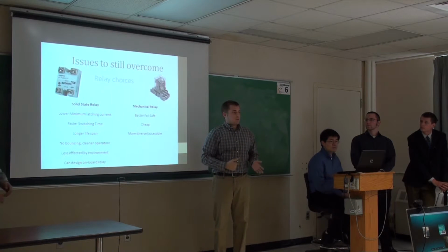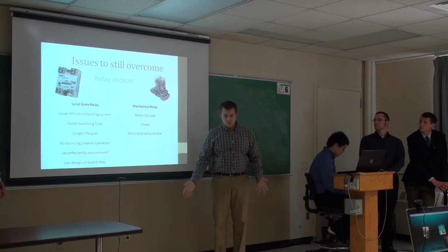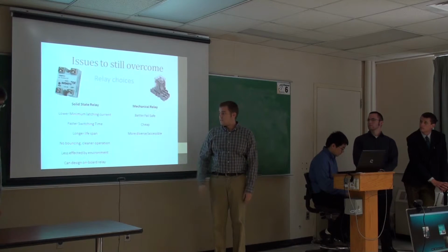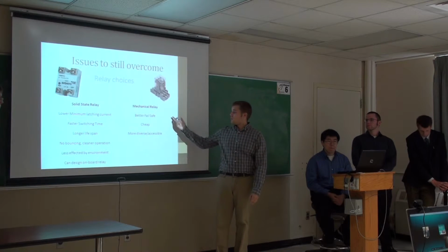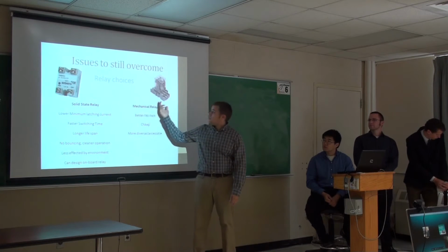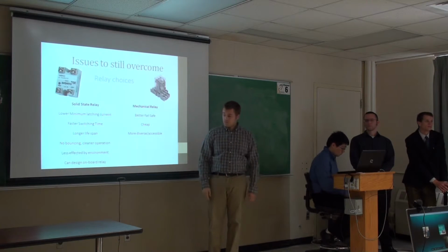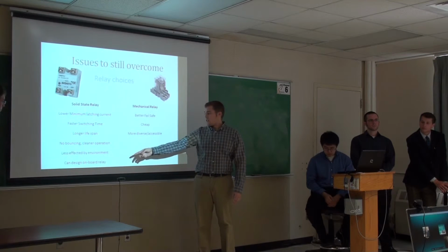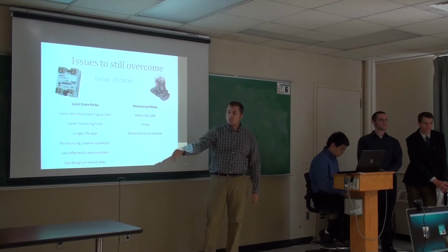It has a switch that moves back and forth. The solid state relay is just circuitry, so it lasts a lot longer. I think the lifespan says it's over 1 million to maybe 10 million switches, so that's quite more than the mechanical relay. It's also less affected by the environment. The mechanical relay can be affected or can affect machinery around it. And then finally, the last option, we can design our own onboard relay if we want to for our project.